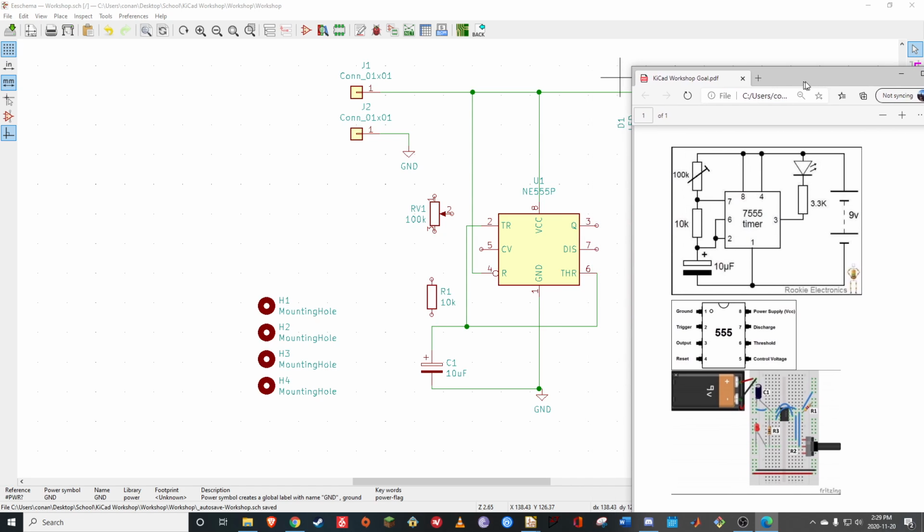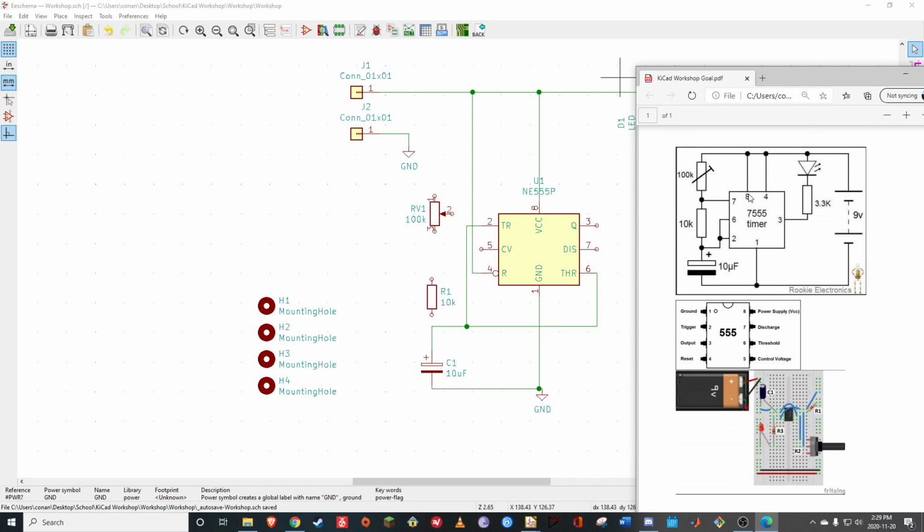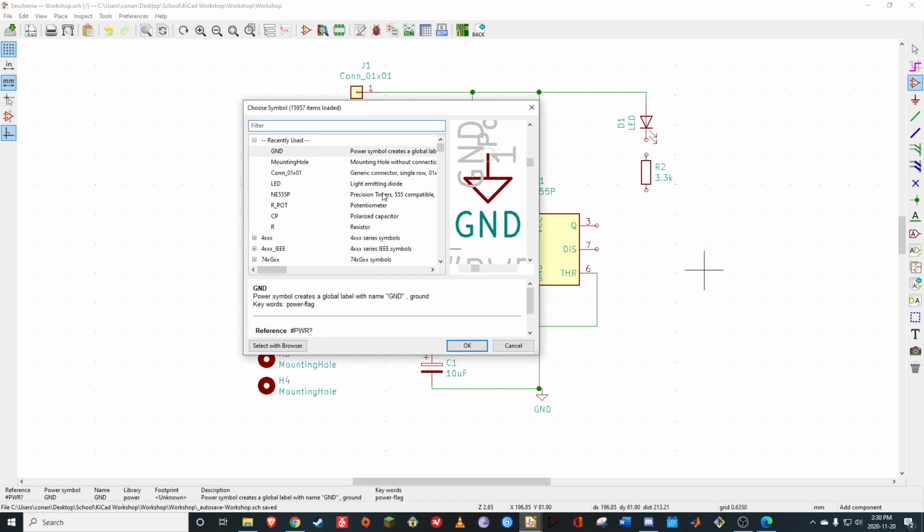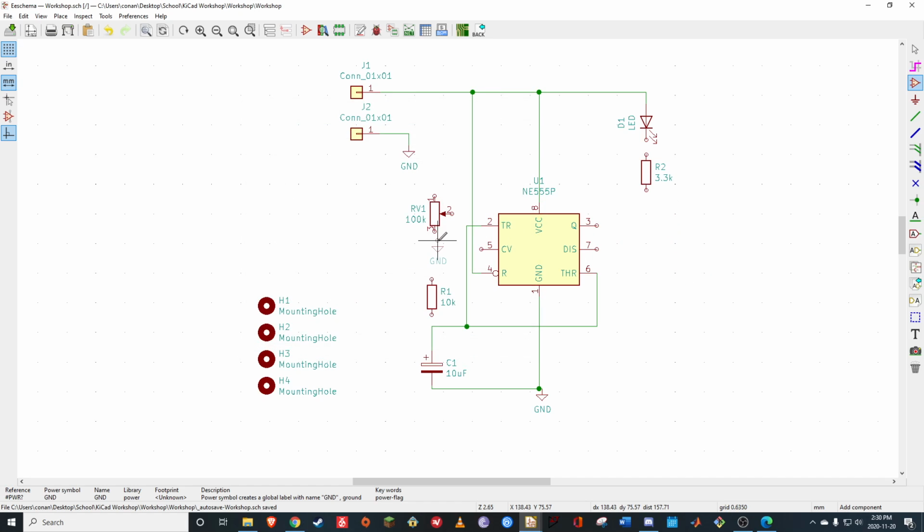All right. Now, pin 8 also goes to the top of our potentiometer here. Now pin 3 on this potentiometer is going to go to ground. So if we want to, we can just put another ground flag there, which I will do just because our lines are already getting messy, and I can tell that that'll be a confusing problem in the future.